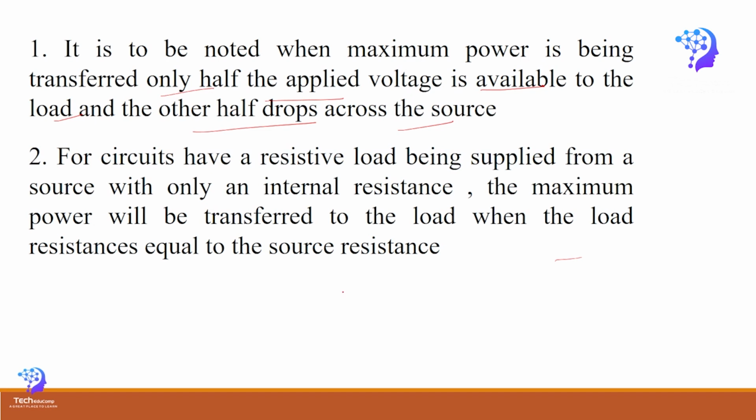As for the second one, for circuits having a resistive load being supplied from a source with only an internal resistance, the maximum power will be transferred to a load when the load resistance is equal to the source resistance, as we have seen in the first two cases. So I hope you understood today's lecture, the maximum power transfer theorem.